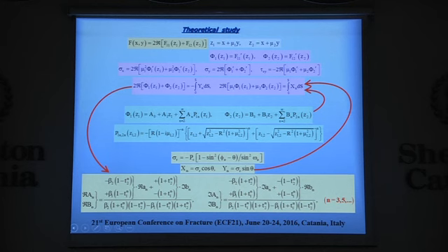However, if I had written down these expressions, we would see that any of these stress components, in the plane state, will be multiplied by the term pC, which is the amplitude of the parabolic pressure, the maximum value of the parabolic pressure, and the contact angle omega 0. Actually, the contact angle omega 0 appears in all these constants we can see here.